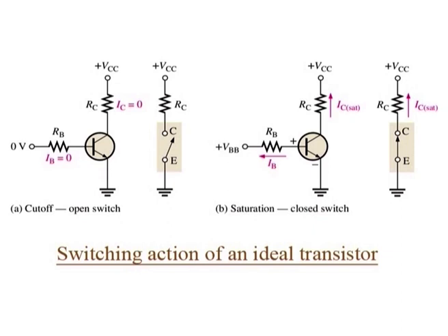In part B, the transistor is in the saturation region because the base-emitter junction and the base-collector junction are forward biased and the base current is made large enough to cause the collector current to reach its saturation value. In this condition, there is ideally a short between collector and emitter as indicated by the switch equivalent. Actually, a small voltage drop across the transistor of up to a few tenths of volts normally occurs, which is the saturation voltage, VCE(sat).